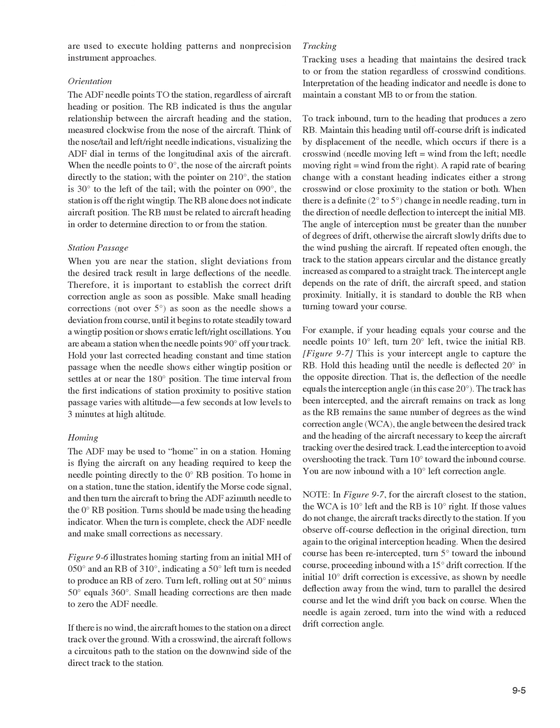Orientation. The ADF needle points to the station, regardless of aircraft heading or position. The relative bearing indicated is thus the angular relationship between the aircraft heading and the station, measured clockwise from the nose of the aircraft. Think of the nose/tail and left/right needle indications, visualizing the ADF dial in terms of the longitudinal axis of the aircraft. When the needle points to 0 degrees, the nose of the aircraft points directly to the station.